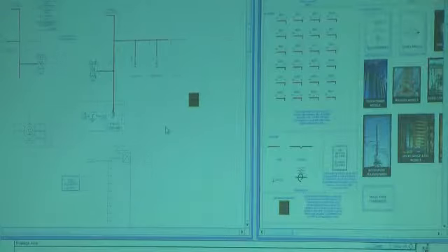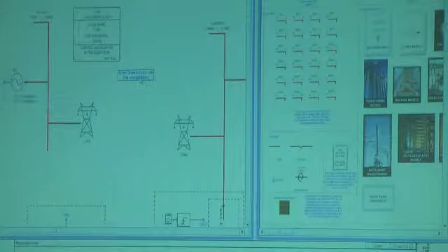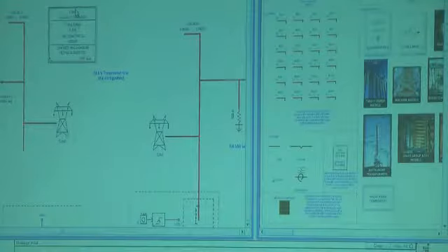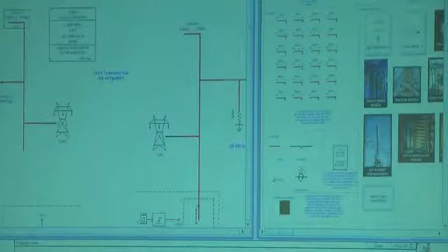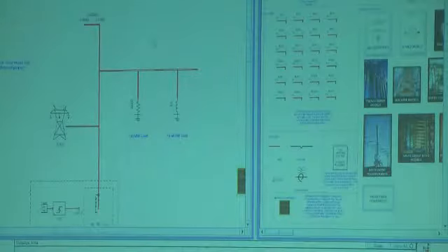So I'm just gonna do a demo for you now, because it's fairly simple. With one rack, you can have a network solution with a maximum of 72 one-phase nodes. So that equals 24 3-phase buses. So we would count this as one bus and this is one bus. So this circuit only has 2 buses. So you could have a maximum of 24 buses on this processor with a network solution.